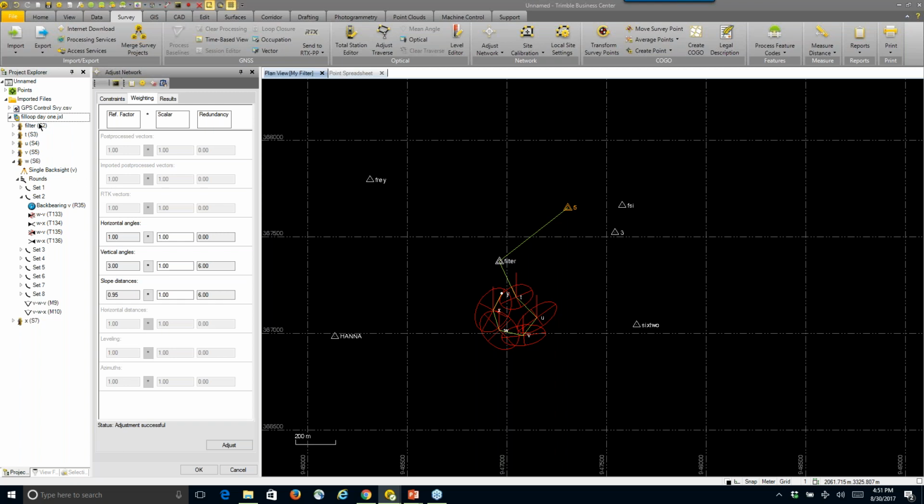But if you have optical and GPS in your project and do an adjustment, it's going to use all available information. So for me, I would try to single out the two different sets, adjust them separately to make sure they're okay, see if I can find any outliers that way, and then bring them together once I'm confident about my information. So that kind of speaks into this follow-up here.